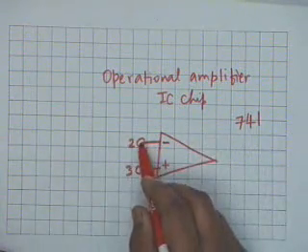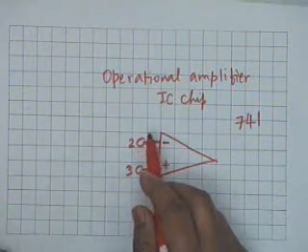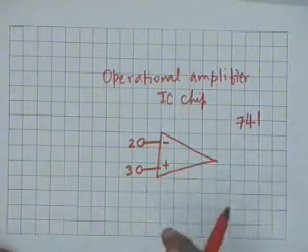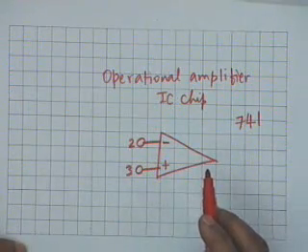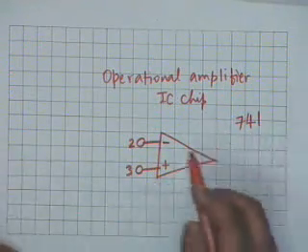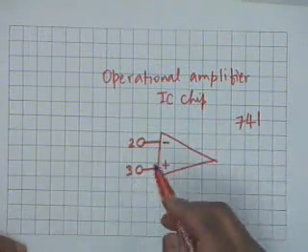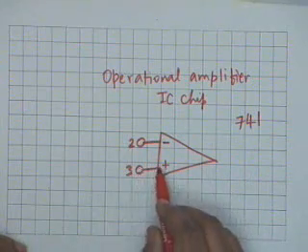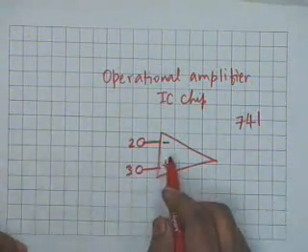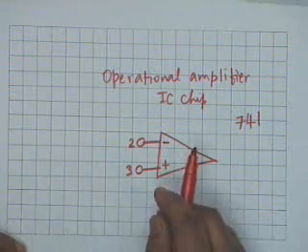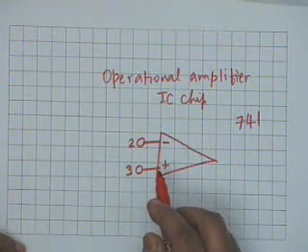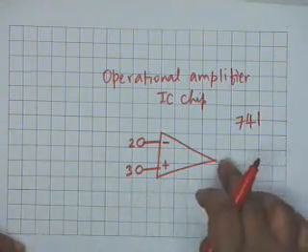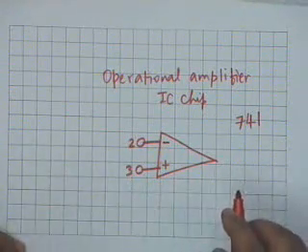That is, if you put a 1 millivolt signal here, the output shall be minus, let us say, 100 millivolt if the gain is 100. Is that clear? There is a phase reversal. If you put a sin omega t here, the output shall be proportional to minus sin omega t. On the other hand, the non-inverting terminal is one which preserves the polarity or the phase of the input. That is, if you put a plus 10 millivolt here, the output shall also be a positive voltage.